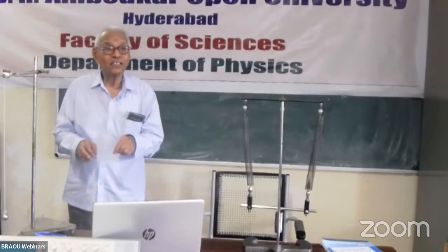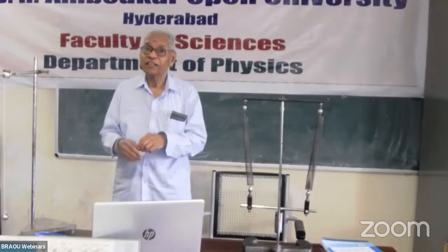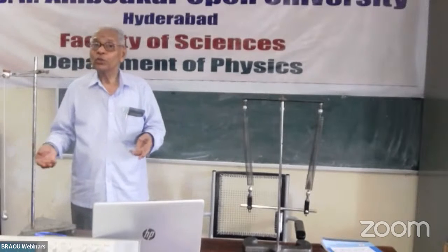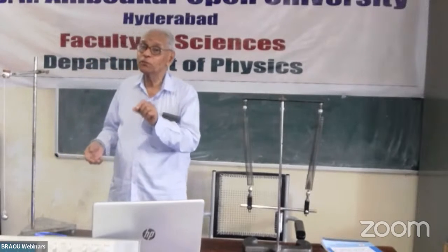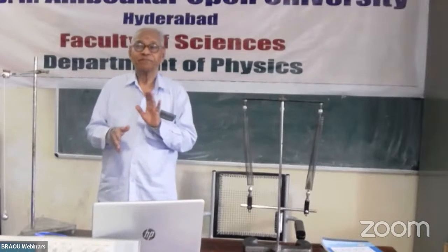It's called an X cut plate. If you do it in the Y direction, it is called a Y cut plate. Each has its advantages. So an X-cut plate of suitable thickness will have a certain frequency.